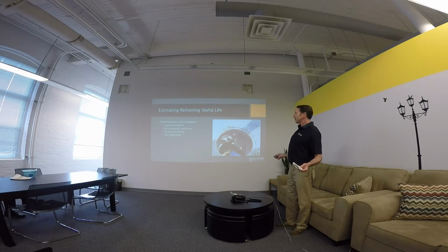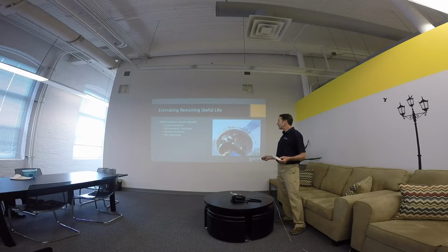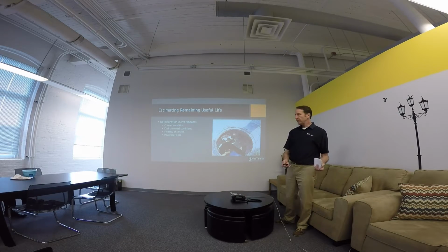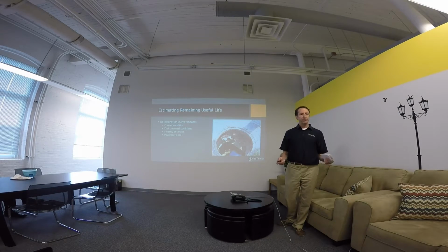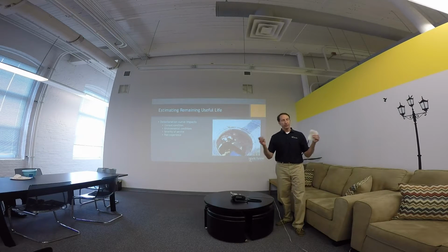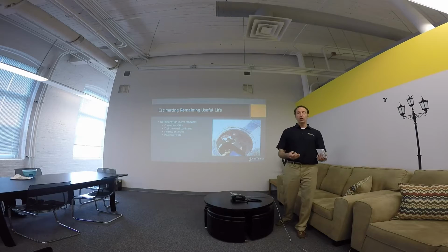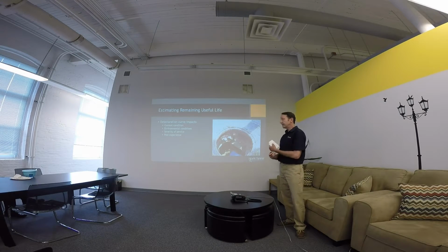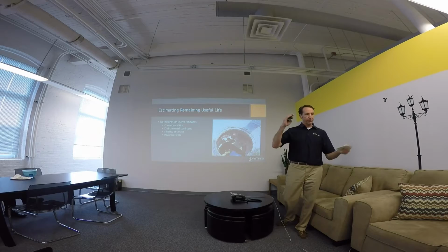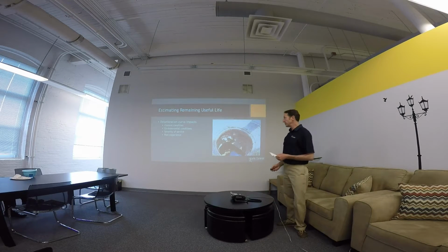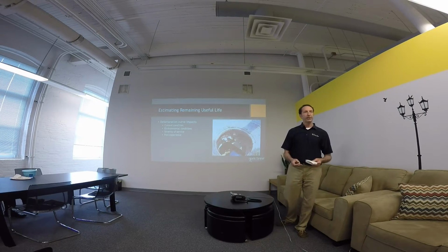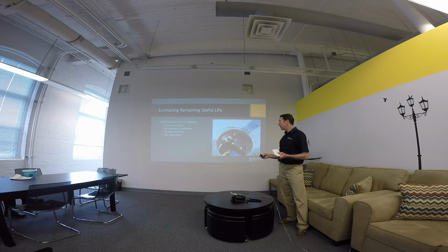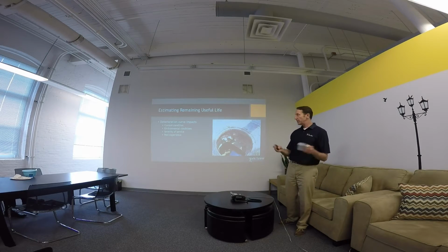So we're talking about estimating the remaining useful life. We have the current condition, we know that. There are also environmental conditions. If the water line is made out of ductile iron, is it in a corrosive environment? Is it going to be pitted early? How long is that going to last? Is it deep enough? Sometimes if it's not deep enough, there may be deflections in the line itself too. Then there's the service: how often is the sewer used? Is it running full? Is it backing up in the manholes? So what is that severity of service?